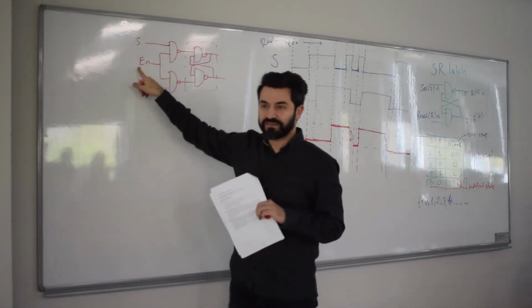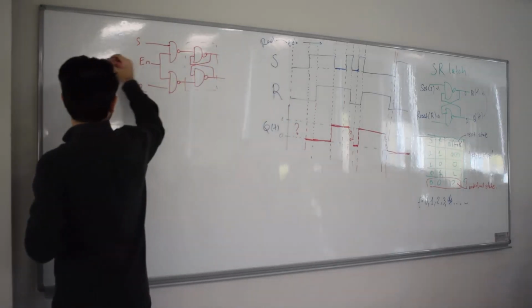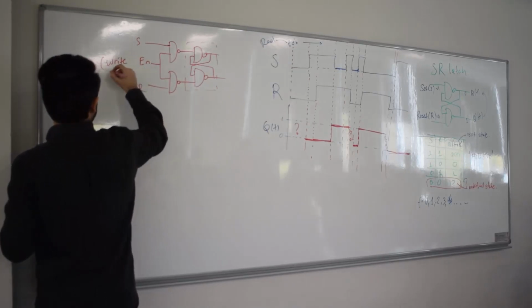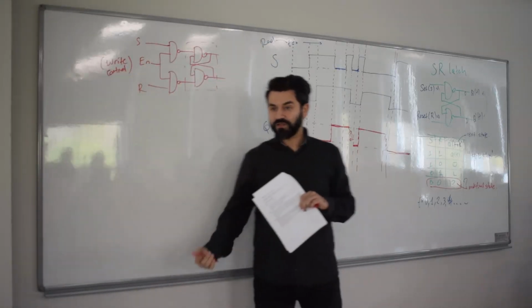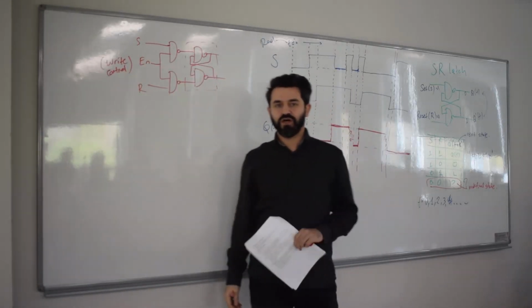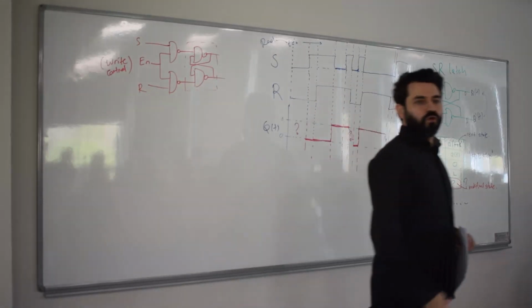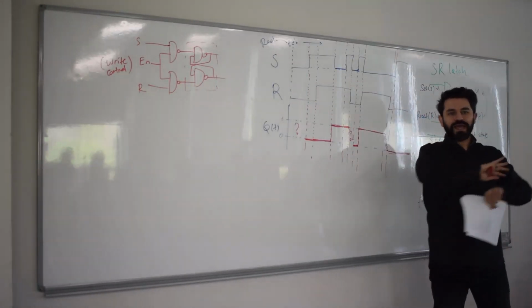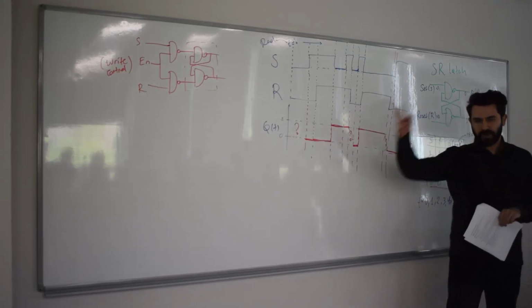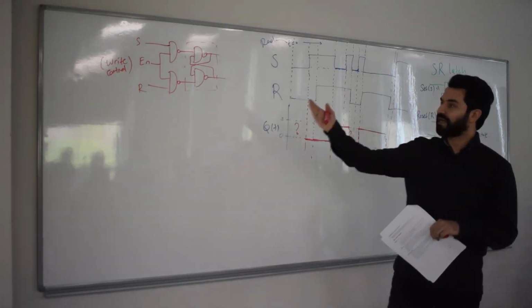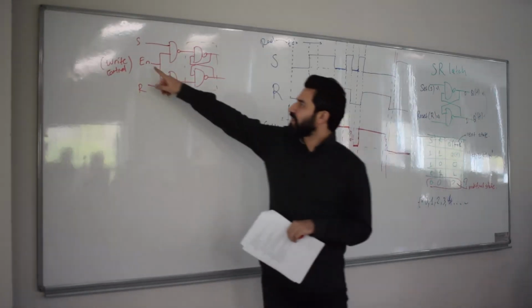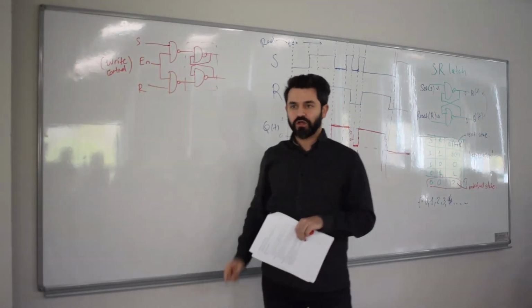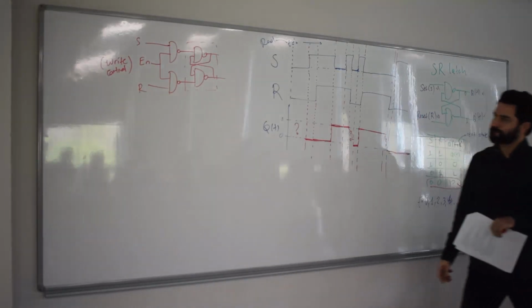This is like a write control signal. You can treat this as a write enable. If you want to write something, you make this equal to 1 so you can have access to this memory element. If you don't want anyone in the circuit to write anything erroneously to this sequential circuit element, then you disable the circuit by setting enable to 0. All right?